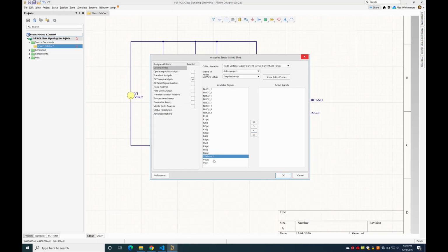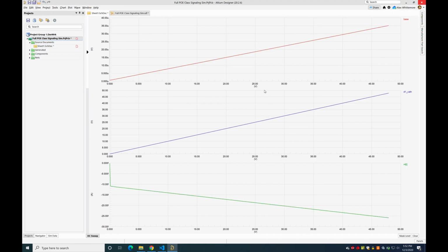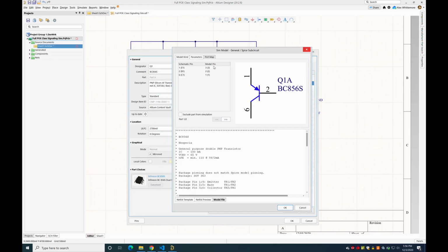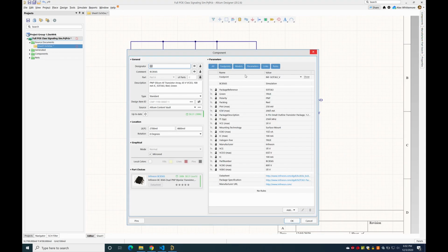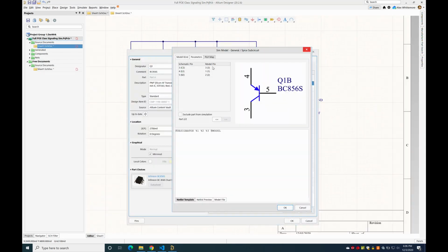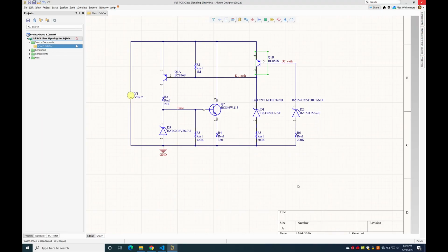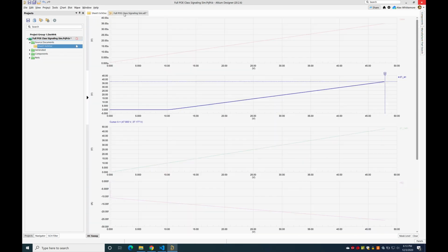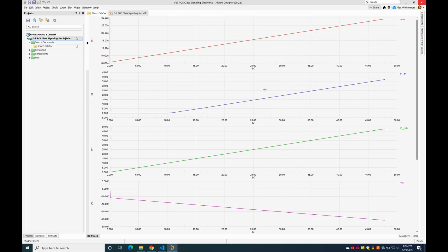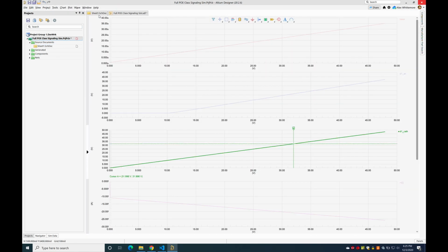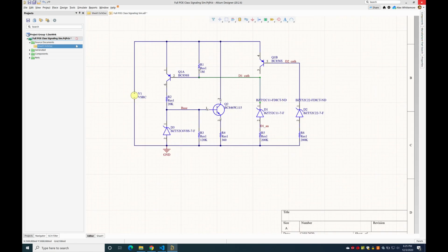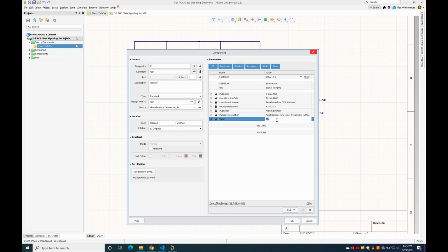Well, I spent the next 30 minutes or so doing everything I could think of to simulate every which way and check which signals were working correctly and which ones weren't. I individually isolated each diode to see that I had them wired up correctly and verified that that was true, and verified that the transistor pinning was correct based on what the voltage nodes on each transistor were doing. And after all of that, I finally remembered my old foe from the last time I tried SPICE simulation, which is that capital M does not mean mega.